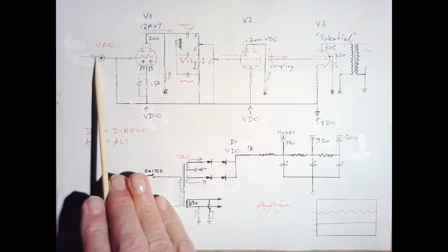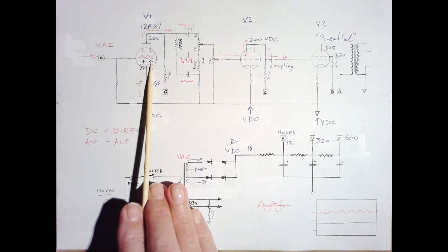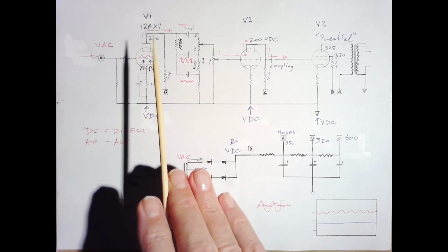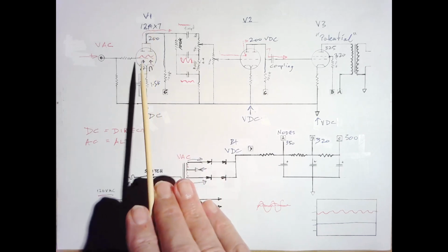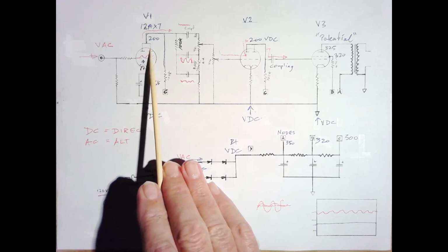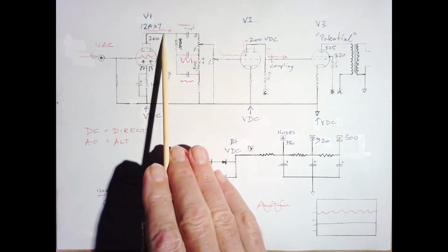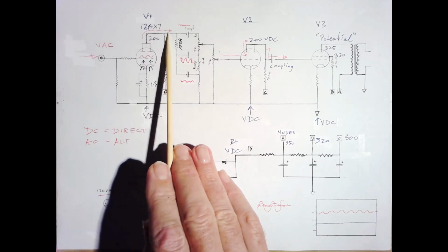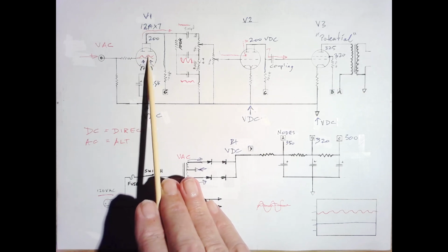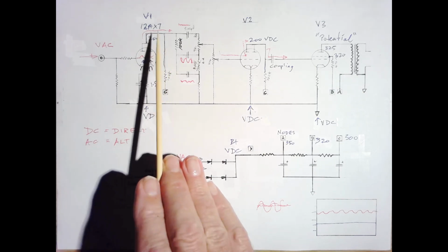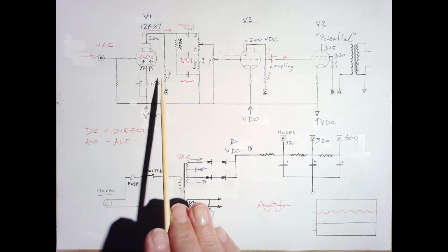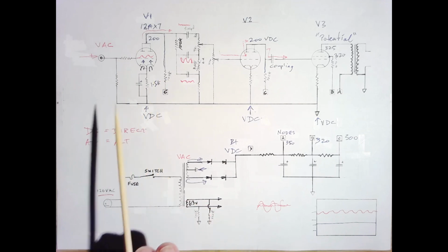But what does happen is our AC comes in here, gets caught up in this rush of electrons going up to the plate, and gets amplified with it. Gets caught up because they're going shazam, shazam, shazam up to our plates here, and the AC gets amplified and carried up through this wiring and on its merry way. The way the AC behaves is determined by the way we have loaded the circuit here with DC and the way we're controlling it with these particular resistors especially.